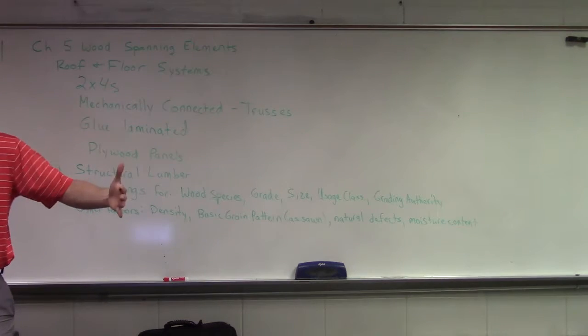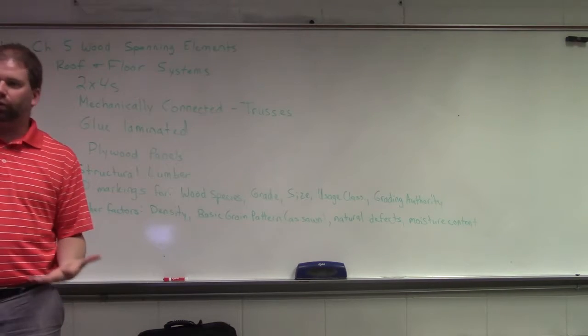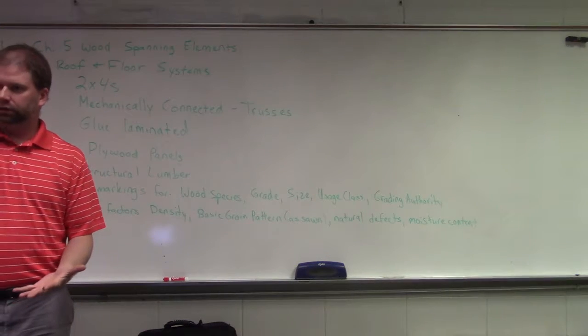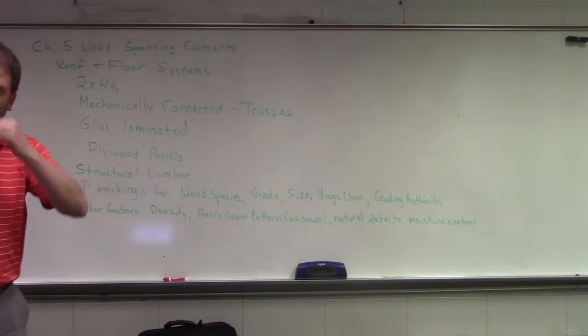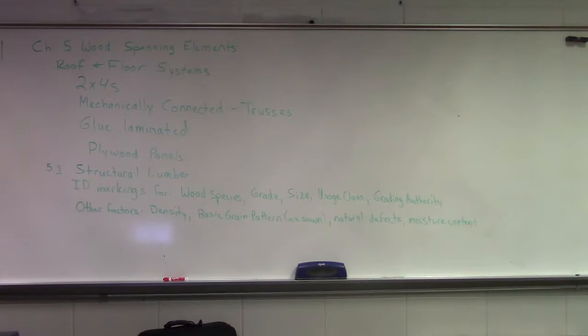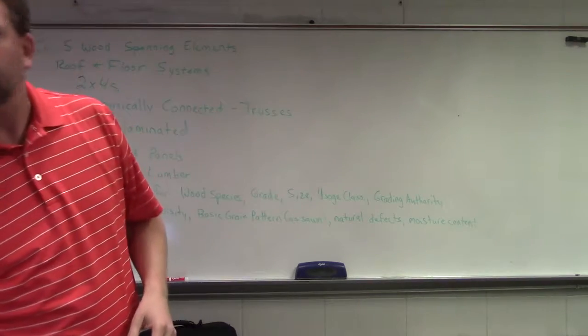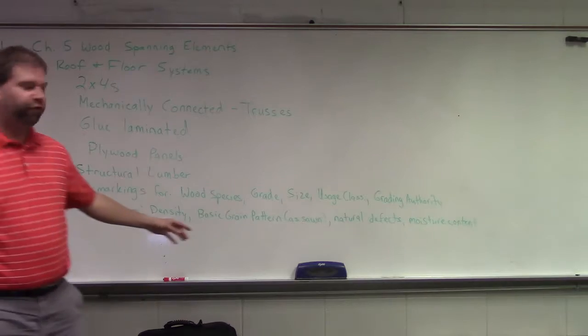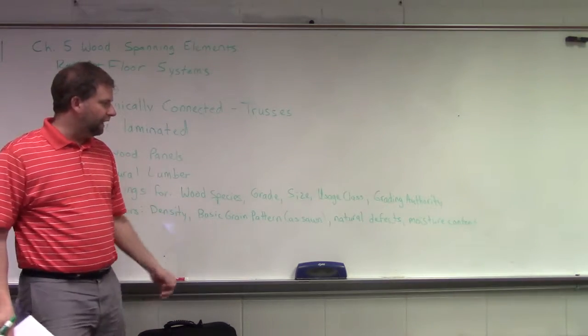If we cast a massive block of concrete, say it's 1 cubic yard, and we want to cut out, instead of cutting out a cylinder to test in compression, say we want to cut out a cube. If we cut that cube out, does that cube care how we orient it? We care because we should be interested in how we cast the thing, so we're consistent with that, but the concrete isn't going to care. Wood definitely cares about how it was cut, okay? So we're interested in that.